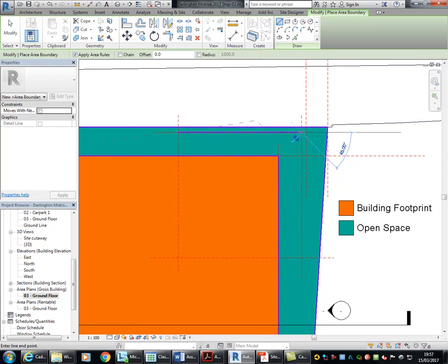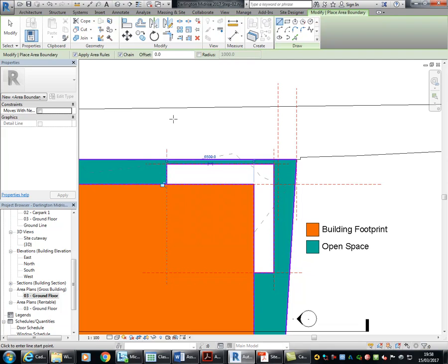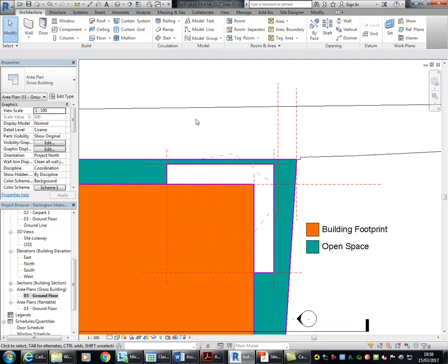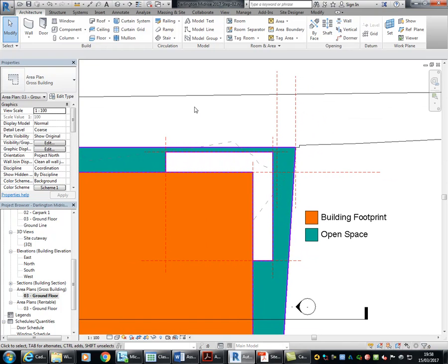And look, it's good when you start thinking about how you can lock things together to make your life easier. It will open up a lot of possibilities for you. But one tip I can give you there is that you don't want to go overboard with it. If you lock too many things together and set too many constraints, you're asking for trouble generally, and you probably end up creating work for yourself rather than reducing it. So just think about when you should be using that lock option.